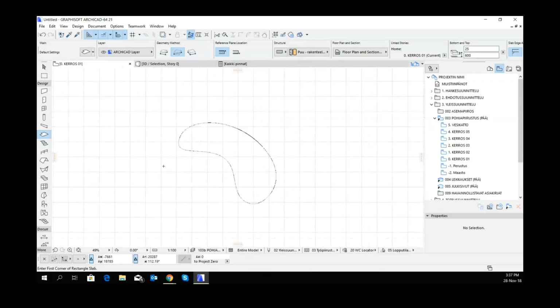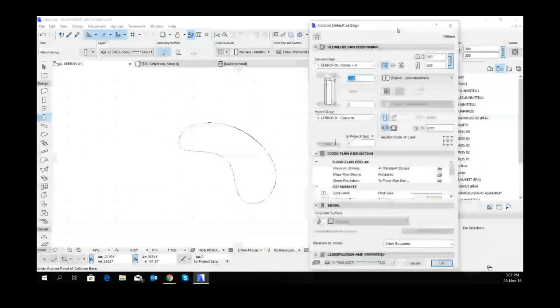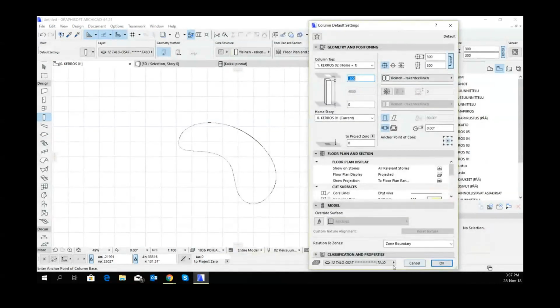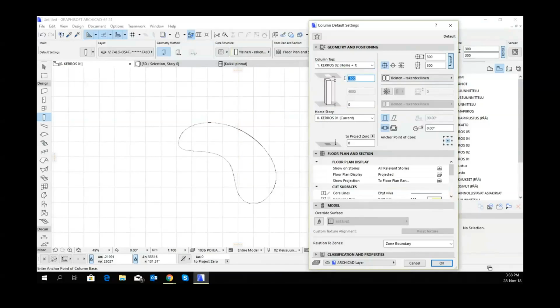Next, we want to put some legs on it, so we might just grab this tool here, a column tool. And choose a side, oh no, sorry, wrong thing there. Oh, we don't want that linked at all. So, what did I say? I made the table top 25. So if it's 600, that's going to be 575 for the length of the legs.